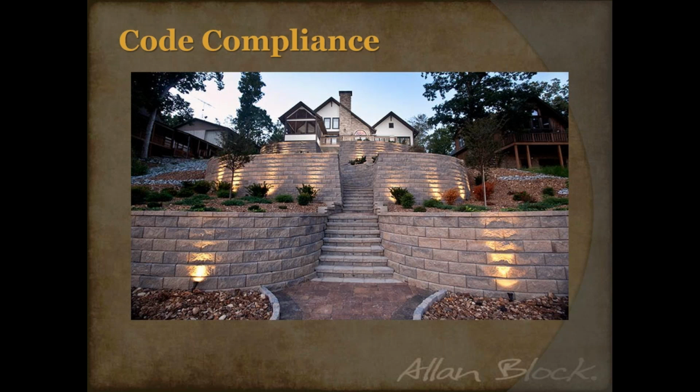If you look pretty closely, you can see that the stairs are actually not tied to the wall itself. They built the wall, and then they did the individual steps between there, but keeping them at 7 inches as opposed to 7 3/4. And you'll see that the wall is slightly taller than the stairs, and that's because they're keeping this true 7 inches all the way up.